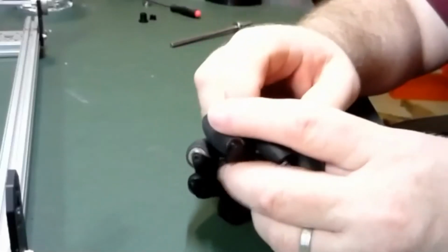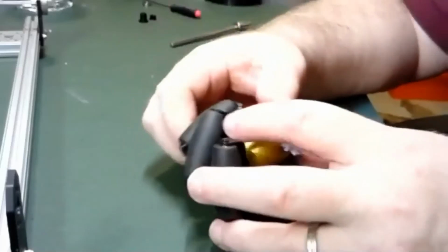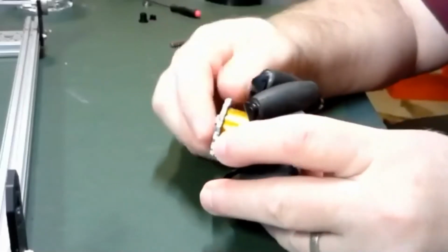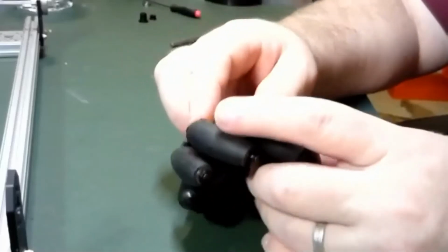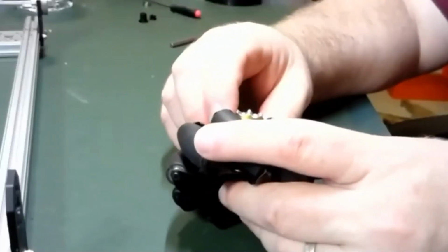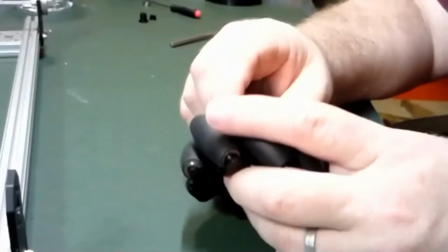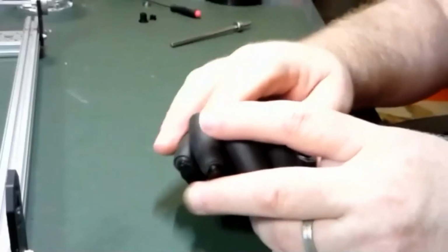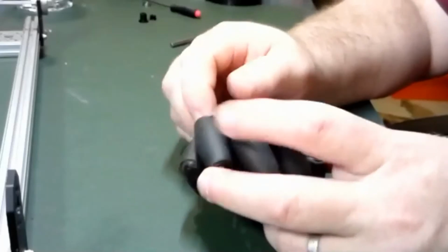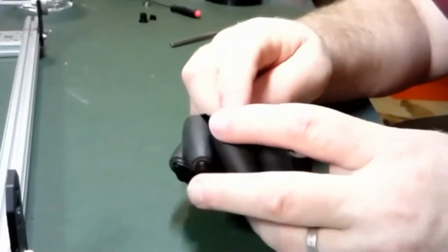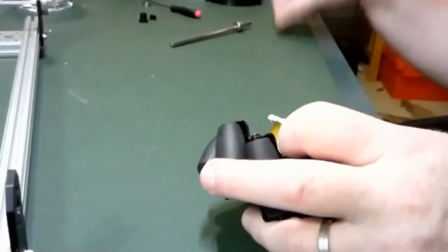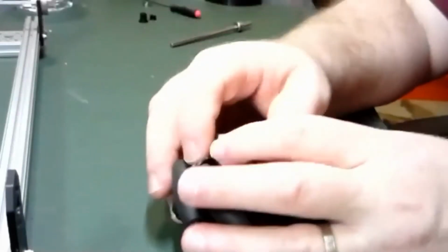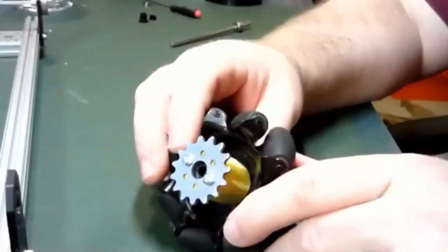Do you need a 3D printed piece if you use GoBuilda Mecanum wheels? GoBuilda has a variety of hubs that they have available that you can use and purchase to make the pieces line up. But then you have to figure out how you're going to get a GoBuilda hub to go onto a Rev axle, or how you're going to take a GoBuilda axle and attach it to Rev parts, or however you want to do it. There's a variety of ways to do that.